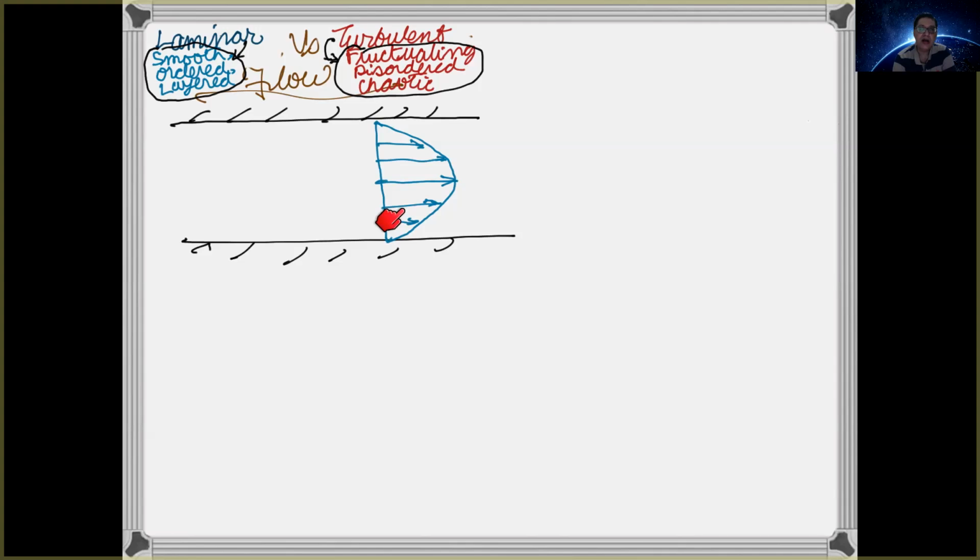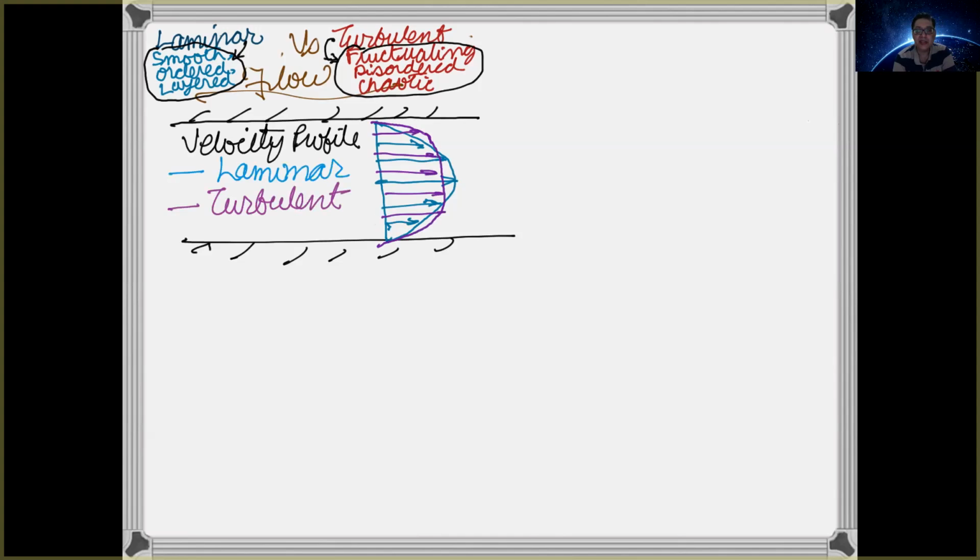And if, let us suppose, this flow velocity for laminar is close to the transition, then for a turbulent flow, for almost the same mass flow rate, you get a velocity profile which is much flatter. So you can see that the streamwise momentum transport in the vertical direction in a turbulent flow leads to a mixing of momentum, and it leads to a smooth, much flatter velocity profile for a turbulent flow.